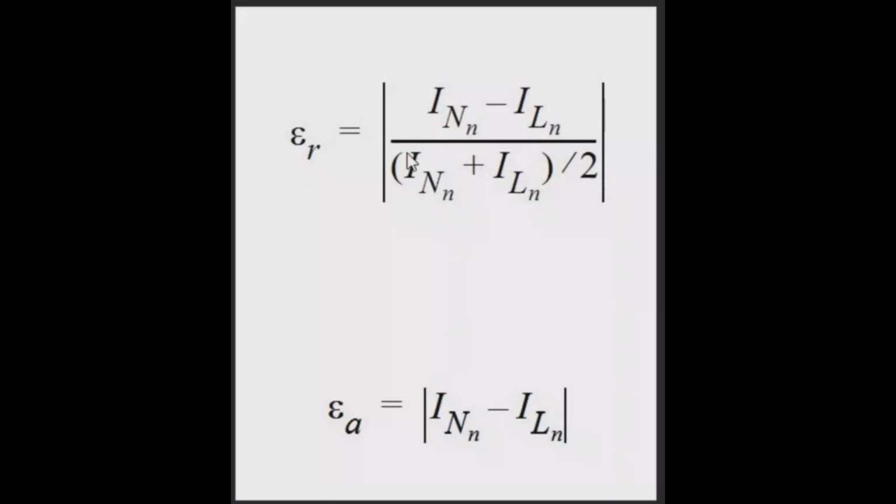That is, it's perfectly reasonable to say that the large components, those power amplifier outputs and such, should be converged within 1% or 1/10% or something like that. But do you really need to have the small intermodulation components converged within 1/10%? That might be, you know, 10 to the minus 9, 10 to the minus 12 amps, which is neither necessary nor desirable because, again, you may have enough numerical noise that you simply cannot converge to that degree.